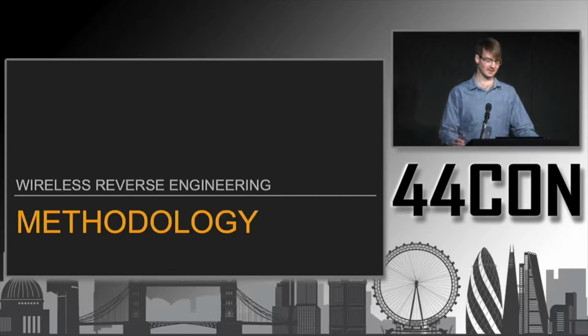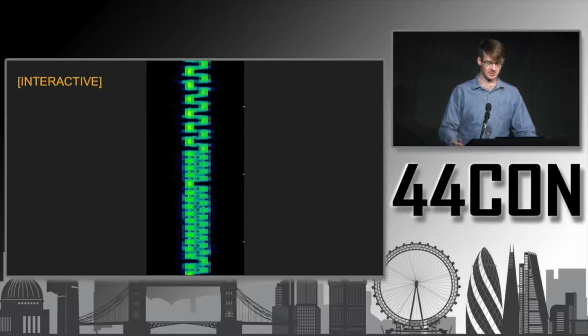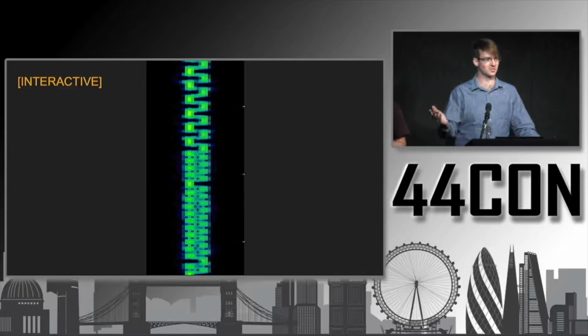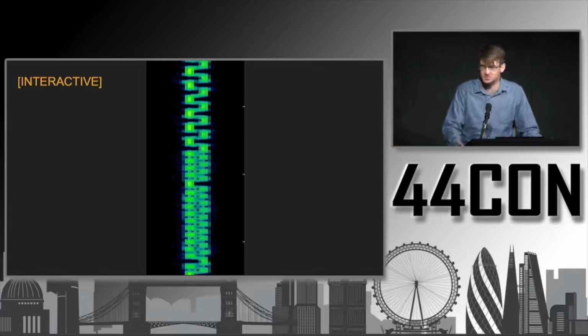But before we get into that, I want to do a little exercise. Here's a picture of a spectrogram of an arbitrary signal, and I'm going to ask some people to take a look at it and volunteer any observations. I've heard a couple people say frequency shift keying, as indicated by the fact that the signal occupies more than one frequency throughout this capture. How many frequencies are represented here? Two, exactly. So it's 2-FSK modulation.